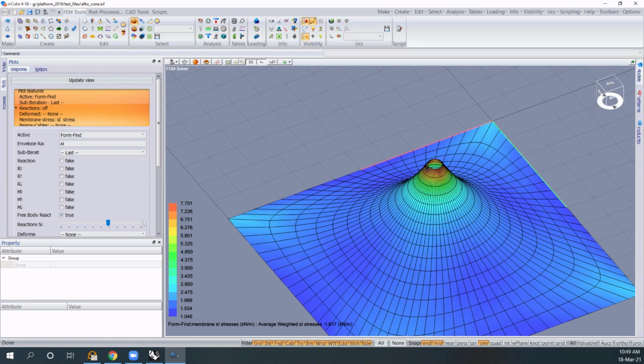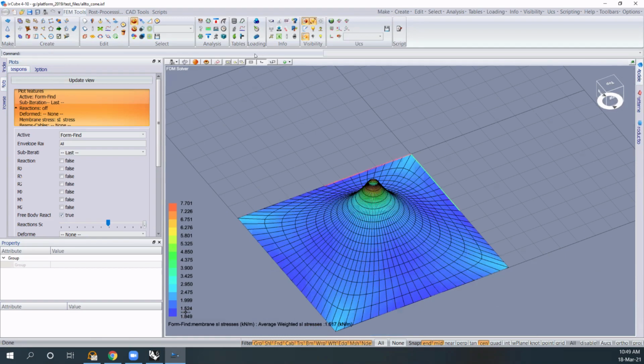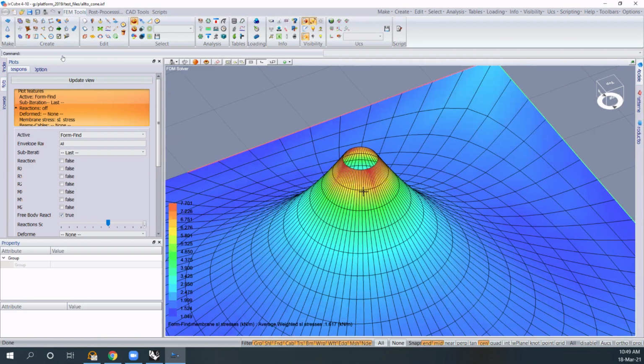The reason why, when we're using the force density method, your first problem is finding a nice balance between the force densities to find the shape. And then we scale it down to, in this case, a good range. You see that everything is almost blue, 1.51 kilonewtons per meter, so it's okay. And clearly here, on the top part, we will need to reinforce this membrane with a double layer or maybe a triple layer. This depends now on the structural analysis. Okay.